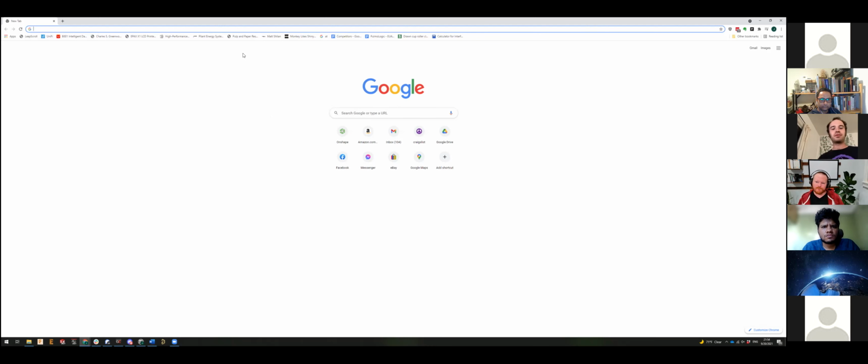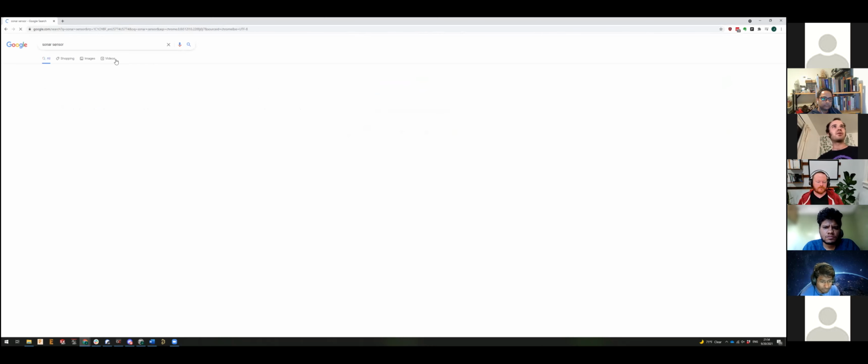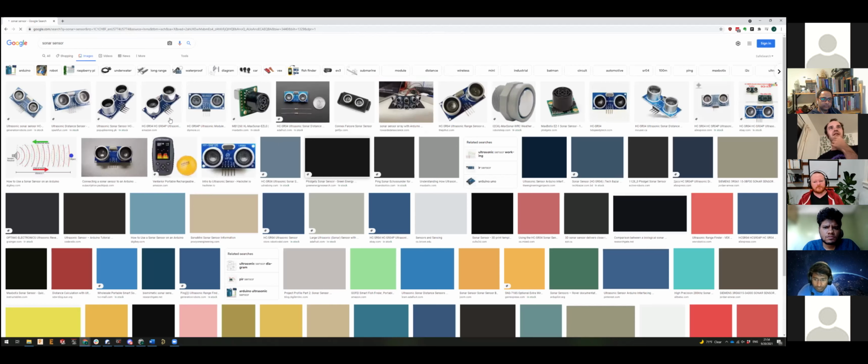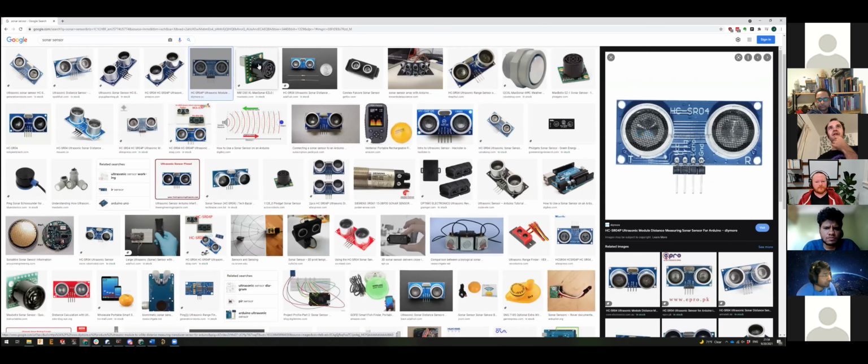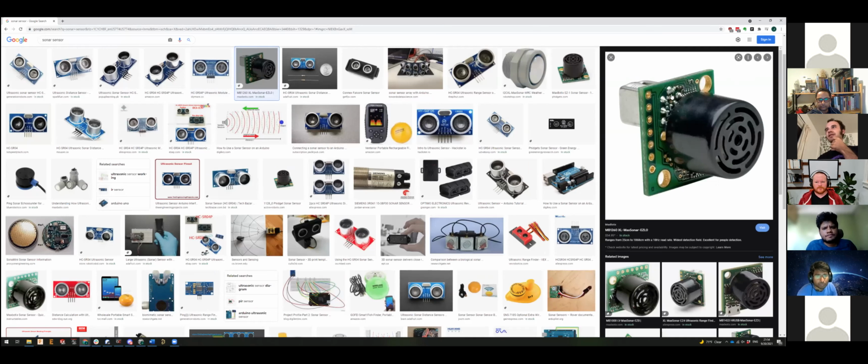I think the most classic example is sonar. In many cases, you'll see an emitter and a receiver pair, but there are many of these, especially in automotive, where you'll actually see a single transceiver. It hits the air, creates the pressure wave, and starts the clock, and then that same transducer actually receives the signal as well. This is where we have dead time, which is one thing you'll encounter with an active sensor. If it's using the same thing to send and receive, there is a timeout while it's ringing down and getting prepared to listen, as opposed to making the sound or the light or whatever it is.